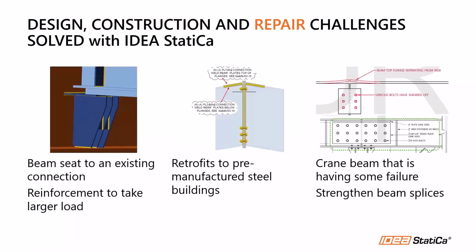Also, we have helped some users to retrofit connections, like adding a seat using plates to an existing connection so it can take more load, right? The other two cases are related to retrofitting moment connections by adding reinforcement plates to the connections. So with these examples, you can see that IDEA StatiCa is being used in different cases that are not only for the design phase of the structural project.